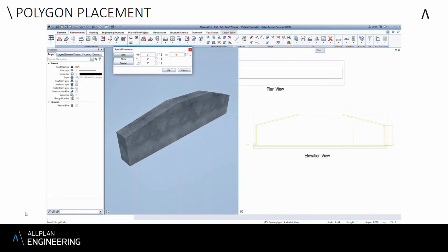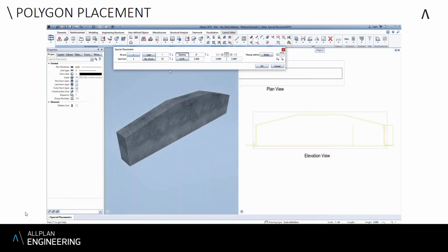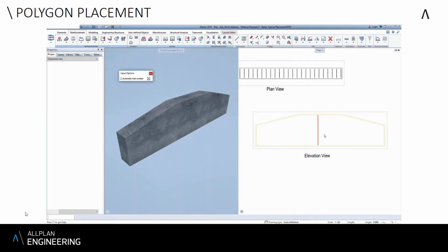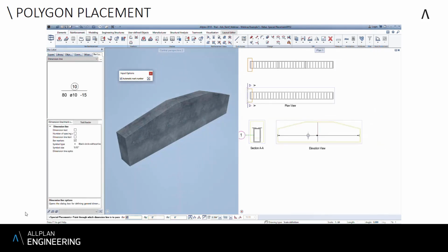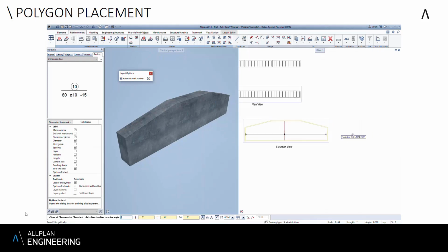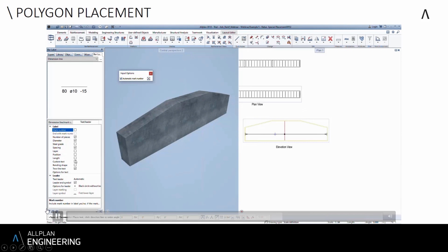So you can change the bar diameter, you can change how it's going to be laid out, the spacing, all of this can be done through nice little input wizards, and then we're also going to have options to change that information later. Once the input boxes have been confirmed, the program will automatically generate the reinforcing based on those inputs. We can choose to display a single bar in the sections for clarity, but we'll see in a second that the reinforcing is complete in the 3D view.